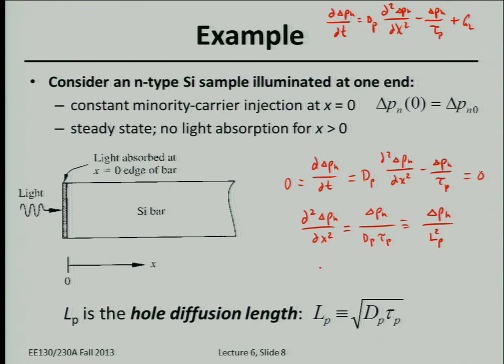To be precise, the diffusion constant is different in each crystalline direction. But for this simple purpose, we're talking about the diffusion length in the direction of the diffusion, the concentration gradient direction, where the concentration is changing. That's the direction the carriers will be diffusing.